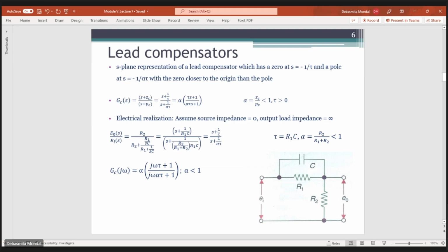By using the compensator, we are modifying the overall transfer function of the system, right? Modification of the overall transfer function means that we are placing the poles and zeros of the compensator in such a way that the root locus or the frequency response of the overall system changes. Since we have a compensator, it will obviously have some pole-zero configuration.